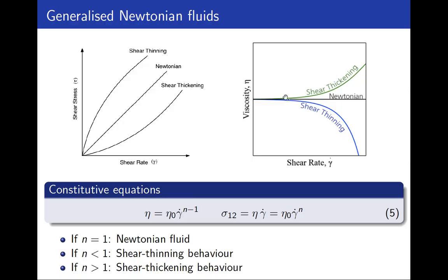But in a few words, with shear-thickening, we observe an increase of the viscosity versus the shear rate, or the shear stress. The higher the force you apply to the fluid, you will observe an increase in the viscosity of the material. So how do we model these behaviors?